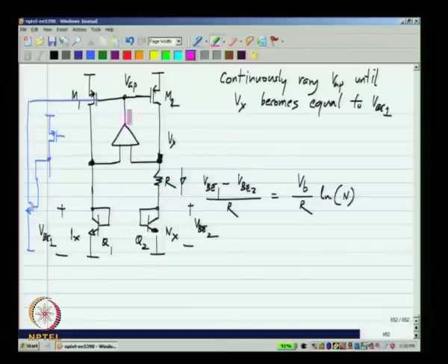Okay. Now, we saw that if the operating point is 0, then the base emitter voltage here will be 0, VBE1 or VBE2. So, we can take this signal. So, if this happens to be 0 at startup, this PMOS transistor will pull the gate of the NMOS transistor up. Let me call this MP and MN. The MN's gate will be pulled up and this will draw a current, and once this draws a current, this VGP will be pulled down and these two will push currents into the bipolar transistors and this voltage will be lifted up. Okay. Now, what must also happen is that if this voltage is lifted up to a sufficiently high value, then this MN should not be drawing any current. Okay.